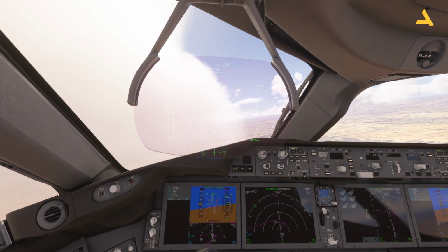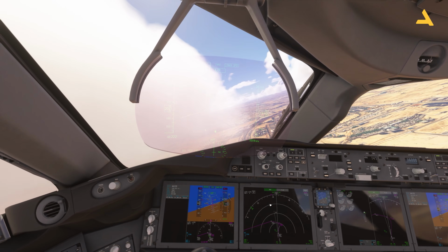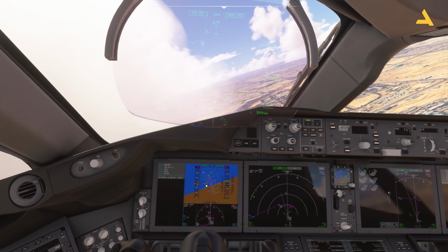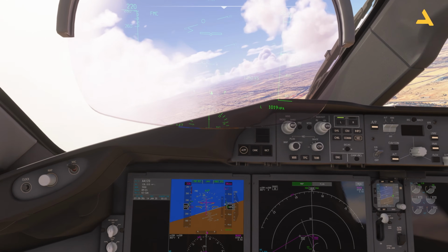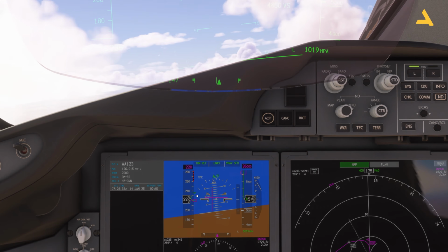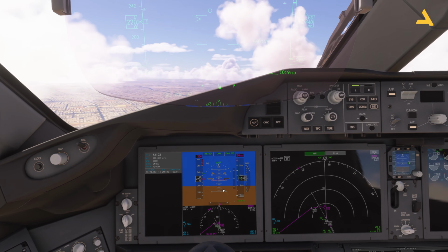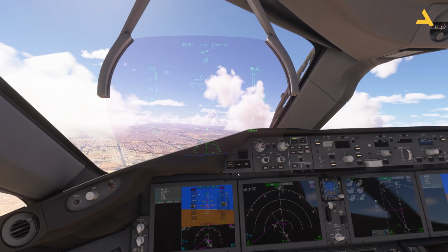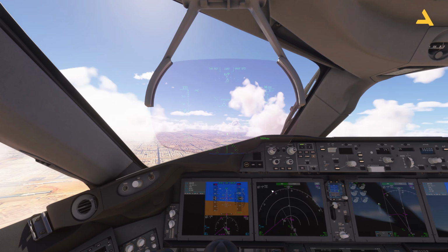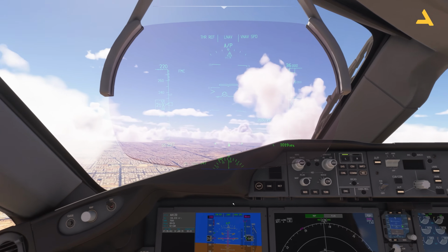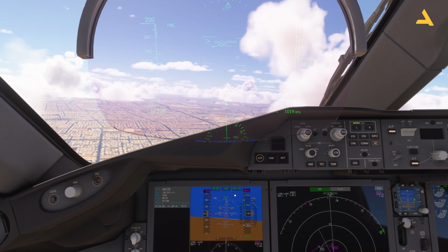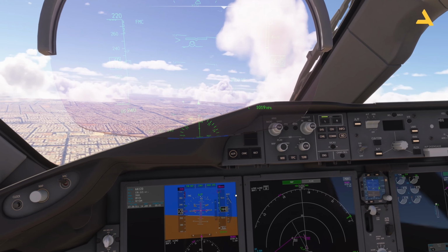And that's it. Now it's good. Now the autopilot is trying to adjust the speed. Above this speed, I can fully retract the flaps, because this is the up speed. The plane can fly without any flaps. Now this part of the primary flight display is the flight mode annunciator, FMA, and it will show you different modes of flight.